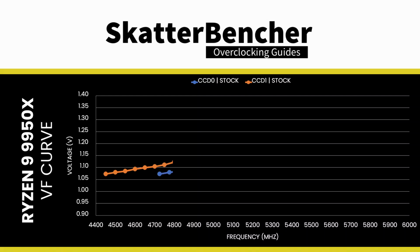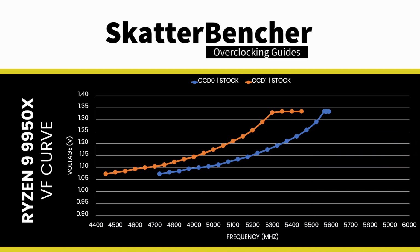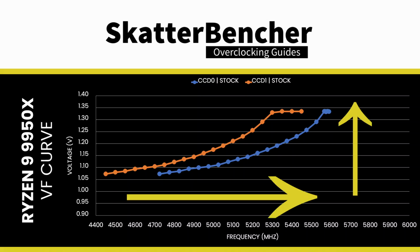Here's the default voltage frequency curve of my Ryzen 9 9950X processor. You'll notice that there are in fact two VF curves. That's because the Ryzen 9 9950X has two CCDs of quite different quality. We can immediately make a simple and redundant observation. The higher the frequency, the higher the voltage we need.